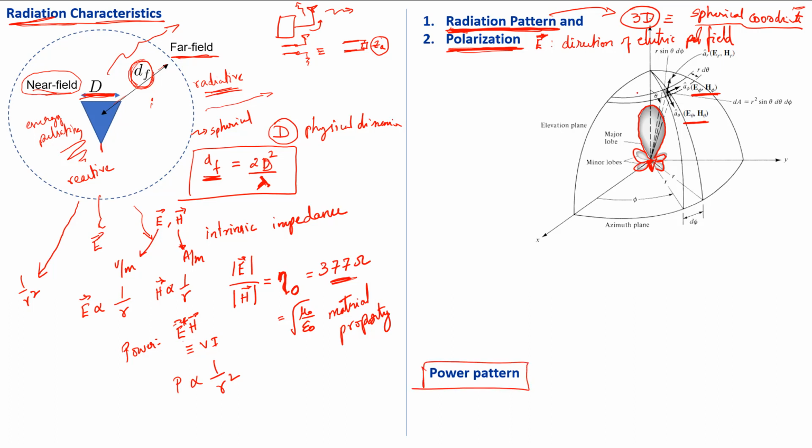That means how much power the antenna is radiating in this particular direction, which is proportional to the electric and magnetic fields and decays at 1/r². What is interesting to note is that once we move out of the near field to the far field, both the electric field and the magnetic field are functions of theta, phi and r. The r dependence is captured as 1/r, and theta and phi can be different for different angles that we are looking at.